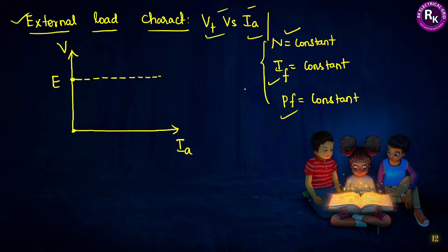So how are these characteristics going to droop? First thing, if your alternator is being operated at zero regulation, then what I can say is this E is permanently maintained. There is no drop in the machine. So this straight line is talking about the zero regulation curve. First conclusion. Now I will bring in some other worse and better parameters one by one.